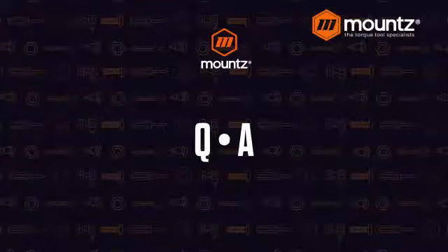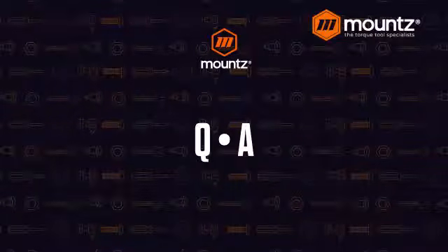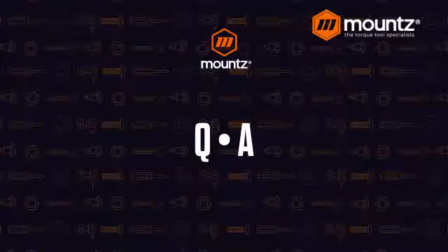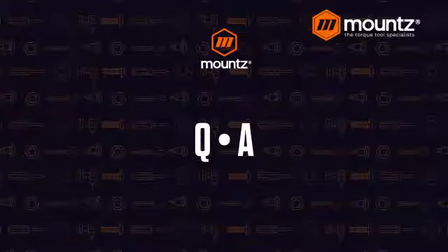All right, great, Dave. The next question is, can a rotary sensor be used for an air tool as well? It can. You can certainly use a pneumatic shutoff tool with a rotary sensor. You could use a pneumatic pulse tool or a hydraulic pulse tool with the sensor. The only tool that you would not want to use it on would be an impact wrench.